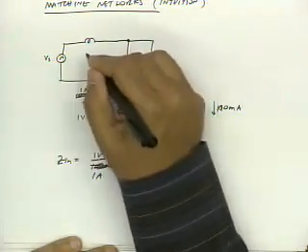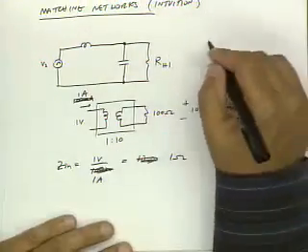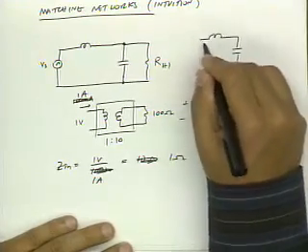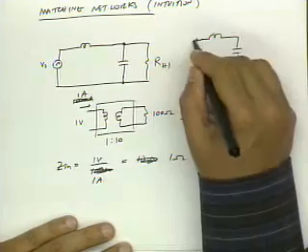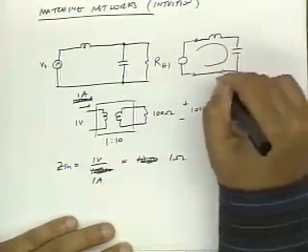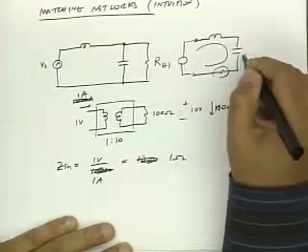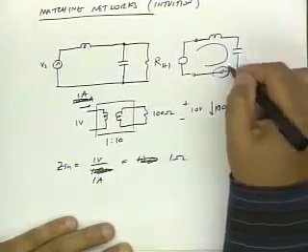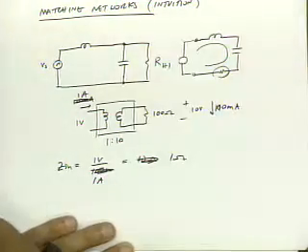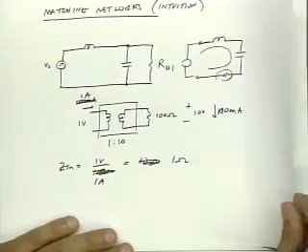So I know that in this circuit, if I have a series feedback circuit, then the voltage across this resistance is going to be Q times less than the voltage across this reactance. So what I really want to do is take advantage of this Q multiplying property to make this circuit work.